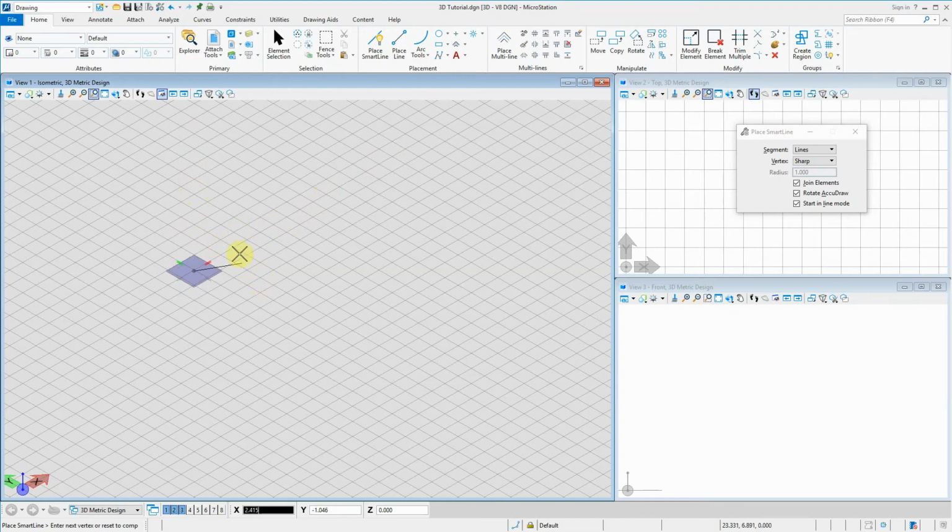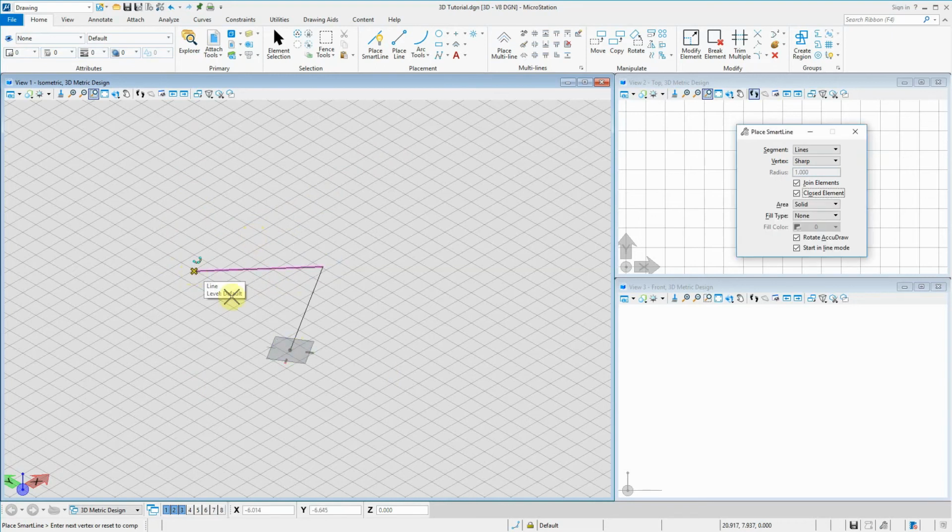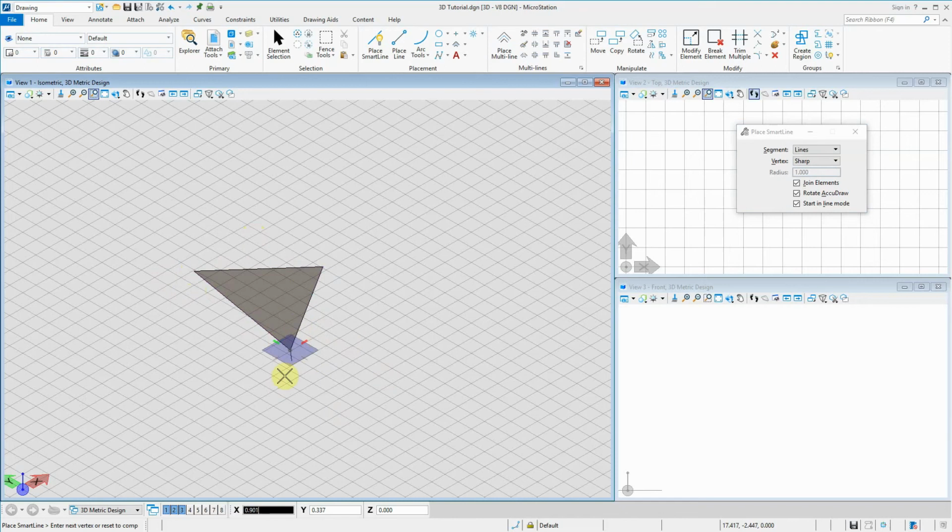Now, this is how you would generally draw in accordance to your origin here. You can change your origin. So let's draw some shape that's not aligned to anything. Also, if you draw closed shapes, they become surfaces. But let's say I want to align to that side, we can use the shortcut RE, right?